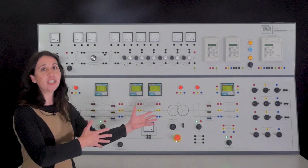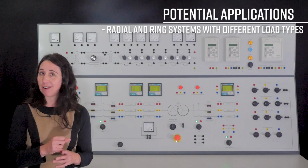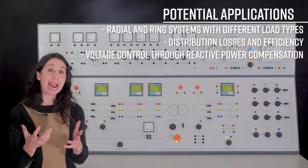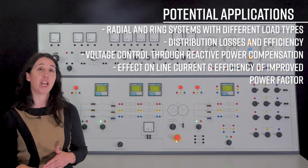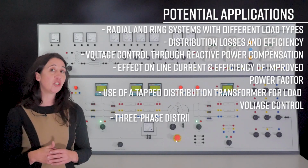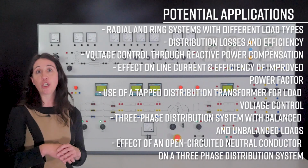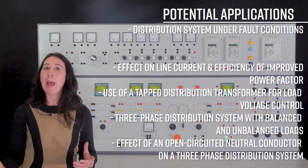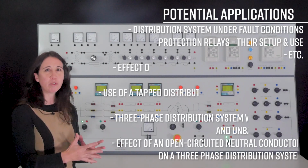To summarise, the power distribution trainer allows you to learn in depth about radial and ring systems with different load types, distribution losses and efficiency, voltage control through reactive power compensation, effect on line current and efficiency of improved power factor, use of tap changing distribution transformer for load voltage control, 3-phase distribution system with balanced and unbalanced loads, effect of an open circuited neutral conductor on a 3-phase distribution system under fault conditions, and protection relays and their setup and use. There's a whole lot going on with this trainer.